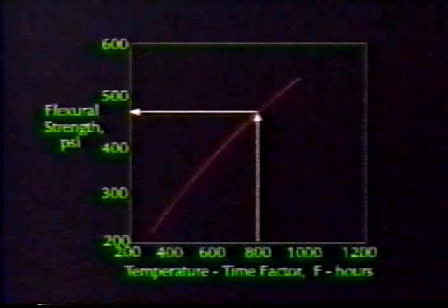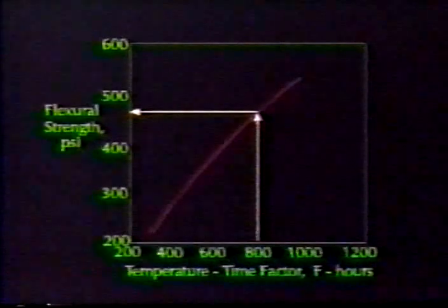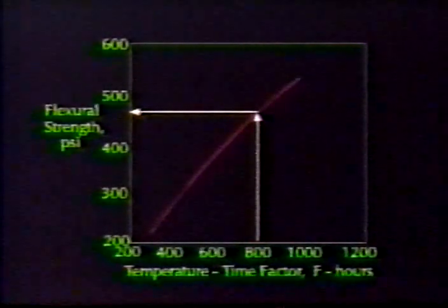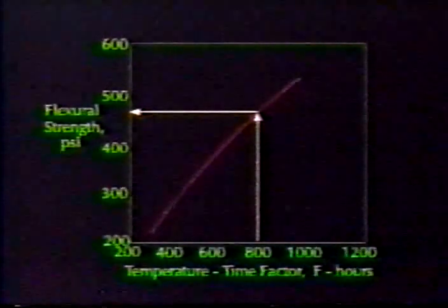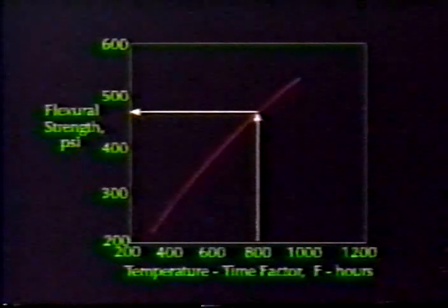For quicker strength developing mixes, the temperatures should be measured at 15 to 30-minute intervals. For slower strength developing mixes, the temperatures can be measured every hour until the specimens reach isothermal laboratory conditions. Specimen strength is determined at different ages. It is recommended that a minimum of 2 specimens be tested at each test interval.